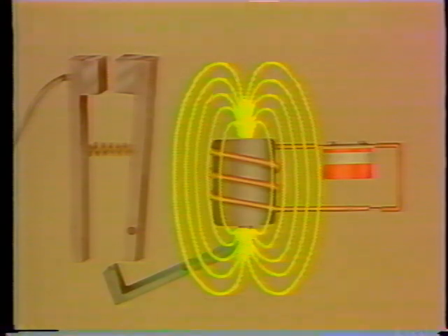For example, here's a magnetic circuit breaker like the one we saw earlier, but the electromagnet is connected to a switch and a battery. The switch might be a switch on your control panel, and the battery might be your plant battery. To open this breaker, you would turn the switch. Then current would flow through the coil. Magnetic action would trip the latch, and the breaker would open.